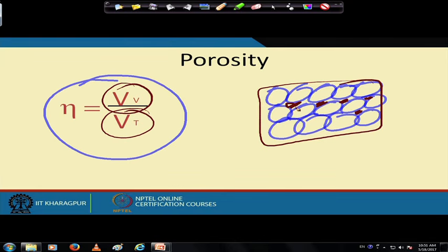So that's another reason why we do compaction on the landfill. If you saw those pictures where we showed that several compactors are used to compact the garbage, one reason is to increase the strength and stability of the landfill, so that the shear strength parameters, c and phi from soil mechanics, are good enough, and the structure is strong and will not collapse. But at the same time, it gets rid of these void spaces. When you compact it from the top, applying pressure, these void spaces will disappear and the waste will get compressed.